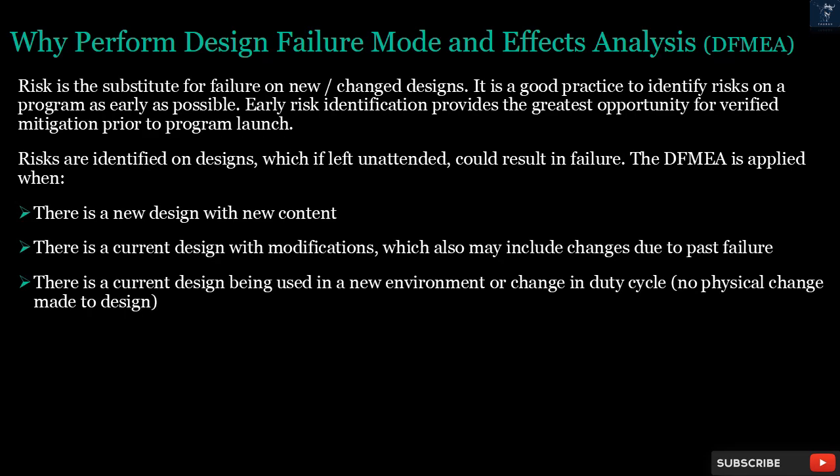The DFMEA is applied when there is a new design with new content. There is a current design with modifications, which also may include changes due to past failure. There is a current design being used in a new environment or change in duty cycle, with no physical change made to the design.